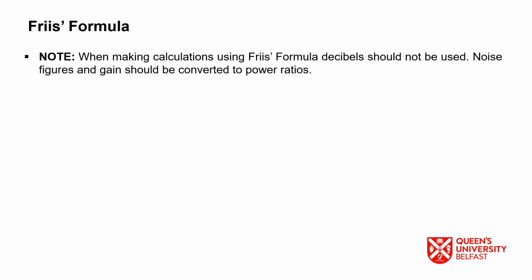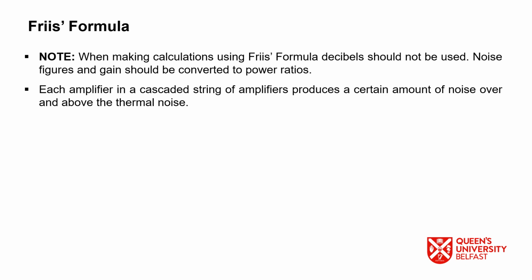Note: when making calculations using the Friis formula, decibels should not be used. Noise figure and gain should be converted to power ratio.